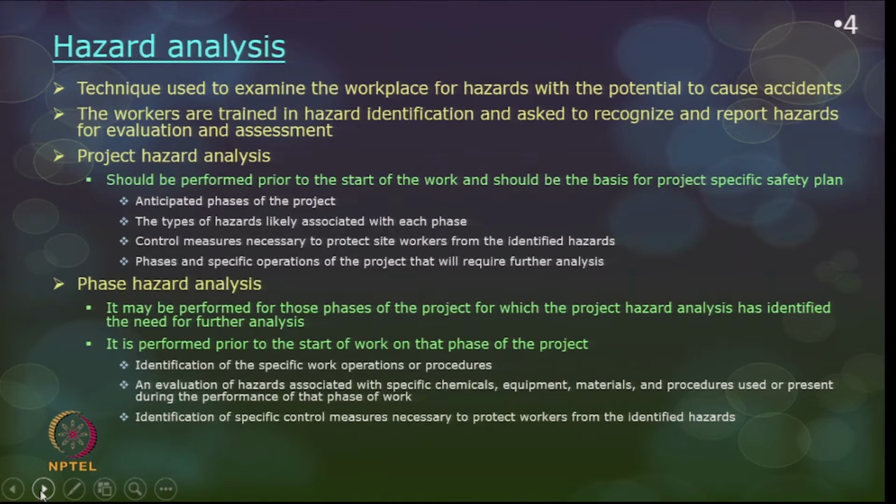All these hazard analyses should be done prior to the start of the work, and during project execution you also have to do safety walk inspections, or walkthrough inspections, safety inspections. If you have a building information model, you can also do a safety walkthrough virtually before the construction starts. So, all should be done.